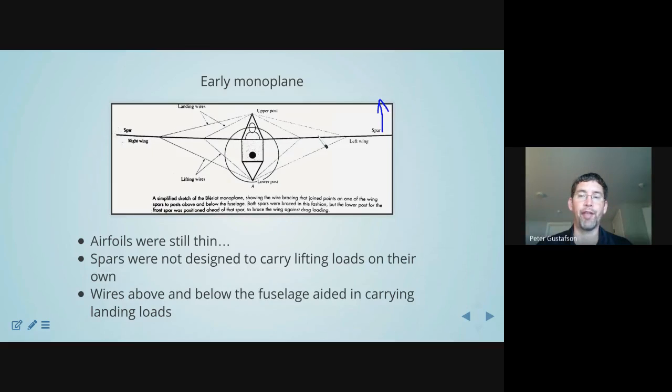In order to offset that bending moment, these bracing wires are generating down forces. Note I only drew one component of the down force, but obviously because these are tension wires, really that overall force should be drawn like so.